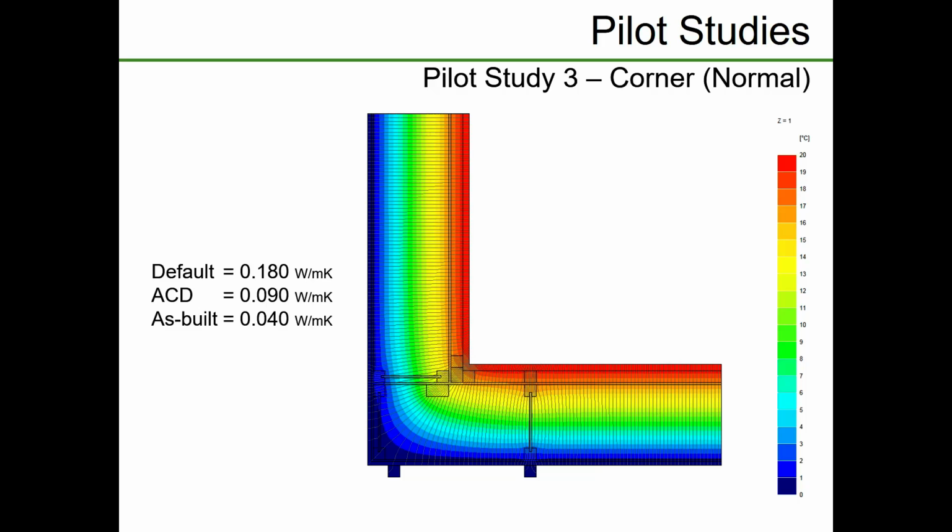I don't like insulating service voids to improve the thermal performance, because it was actually the other side of the vapour barrier, because the vapour barrier in this instance was at the sheathing. Okay, I don't like putting any insulation on the warm side of the vapour barrier. And in the as-built, there was obviously no insulation here as well. So the contractor had to put a batten in the corner because he needed to fix the plasterboard somehow, and missed out that bit of insulation.